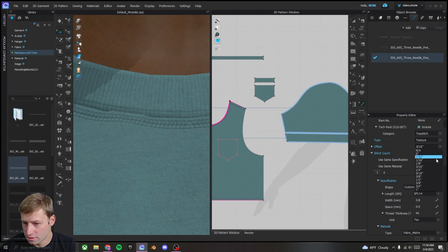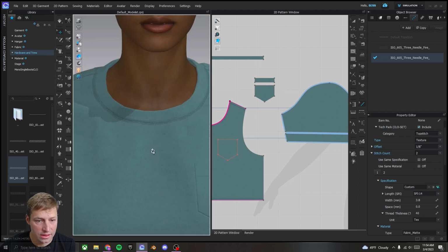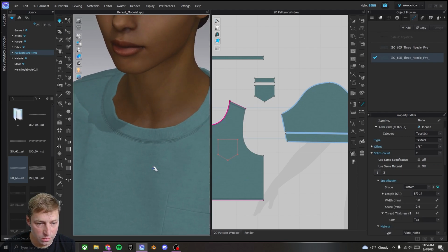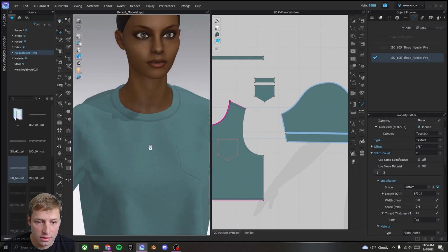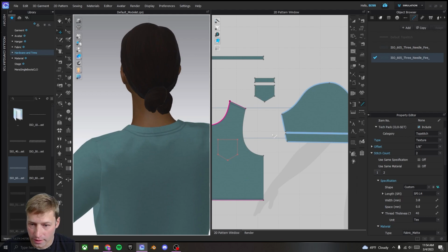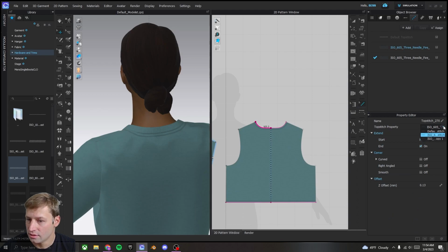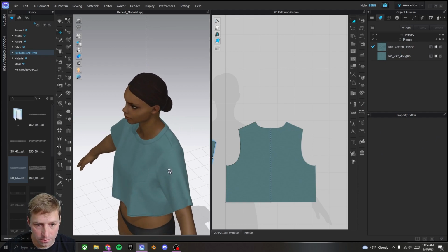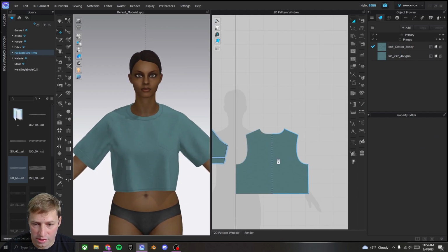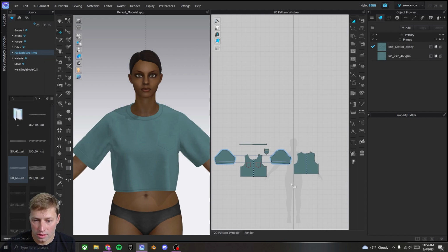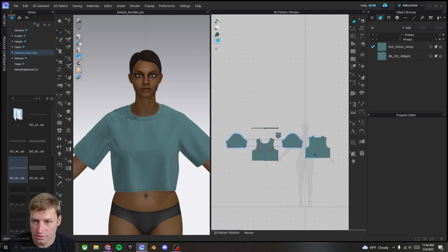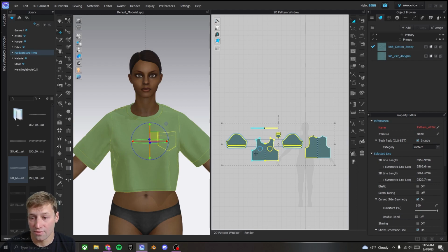And 3/16. So that 1/8 is looking pretty good. Space bar to kind of get that to sync again. And then we're going to do the same thing on the back. So again, using our edit top stitch, click on that, and top stitch property, choose the one that you want. And that'll get it all updated. So now we're pretty much set. So we're going to zoom out, make sure all our pattern pieces are here, using A, hide, select everything.